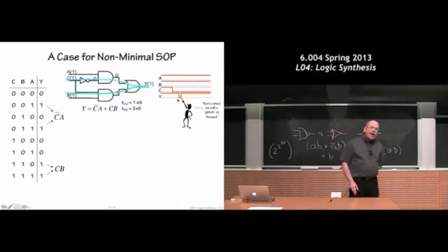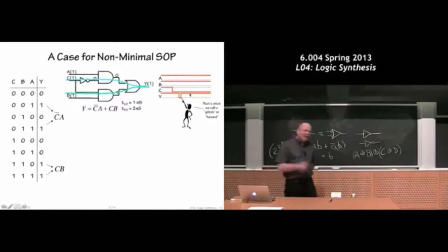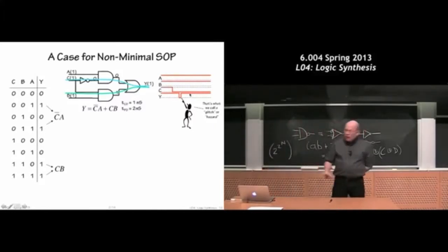And you can sort of say, well, that's okay, Chris. The TPD of this gate is out here somewhere. And in fact, if I waited after the C input changed for the appropriate TPD, I would in fact get a 1 on the output. In some sense, you shouldn't get all upset about this glitch.